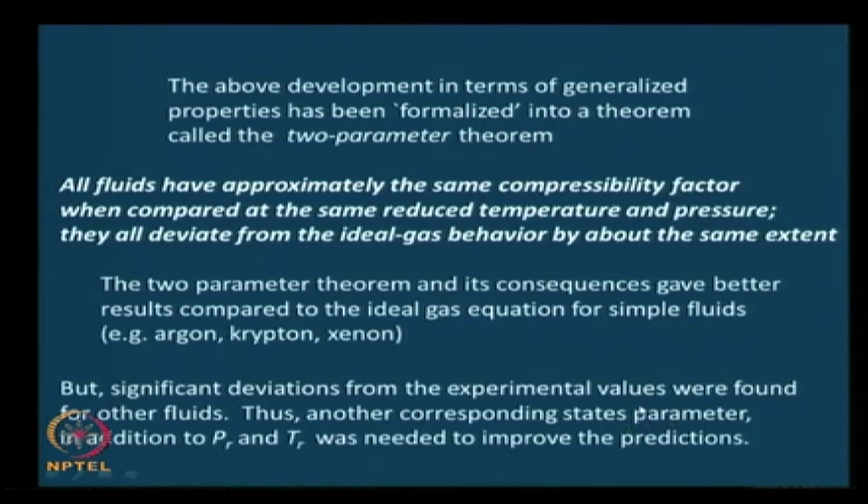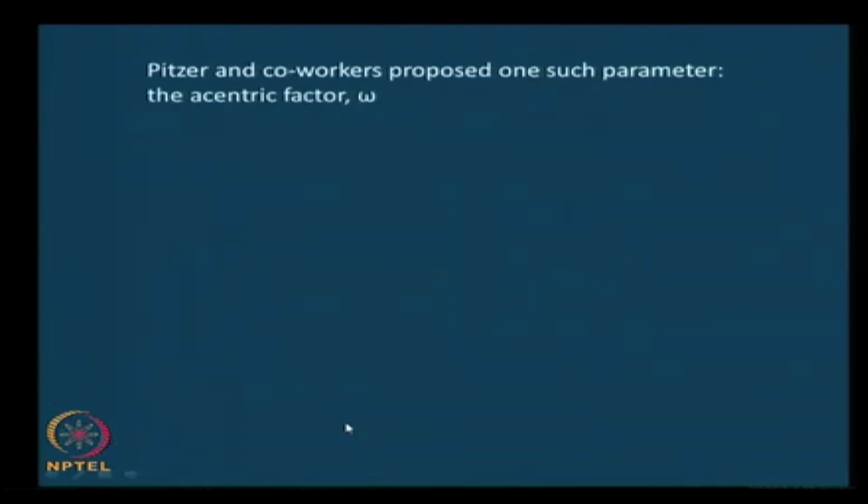Compare this phrase, corresponding states parameter, with the theorem here: all fluids have approximately the same compressibility factor when compared at the same reduced temperature and reduced pressure. You would understand why we are calling this a corresponding states parameter. And when the third parameter was looked into to improve the predictions, Pitzer and co-workers came up with a parameter called the acentric factor, which we will represent by the letter omega.